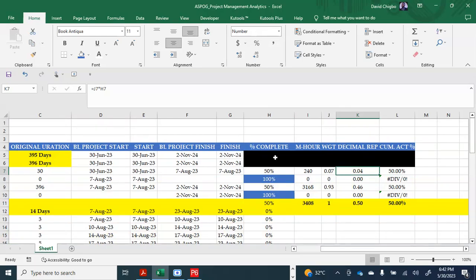All this percent complete. What you'll be working with is this percent complete. Whatever you get from the site activity in real time, you add it. If it is 20%, you add 20% here. But you have to tie everything with formula first of all, so that it will be very, very easy. Once you program everything like this, you start entering your percent complete and it is automated, right? Let's say I put 100%. Just watch this. This is the overall. Then 100%. See that now it's 100% complete.